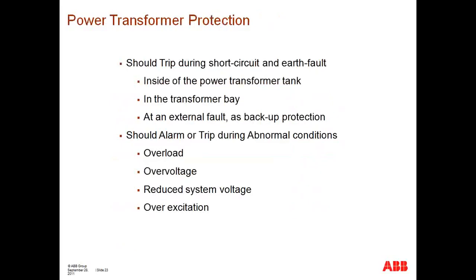So what are some of the requirements for power transformer protection? Well, it should trip during short circuits and ground faults inside of the power transformer tank. And in some cases, depending on the scheme, it's also important to trip at external faults to provide fast backup protection. Again, we're discussing multifunctional microprocessor relays, and most of the ones available in the market have this capability.